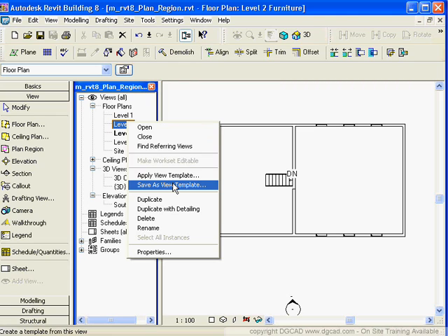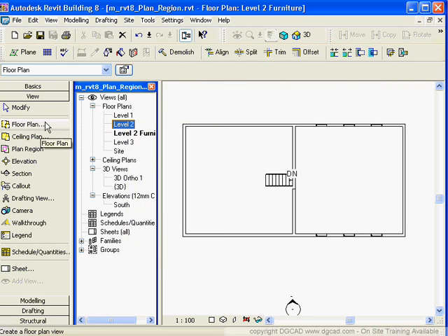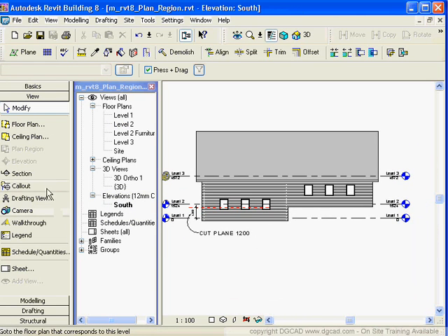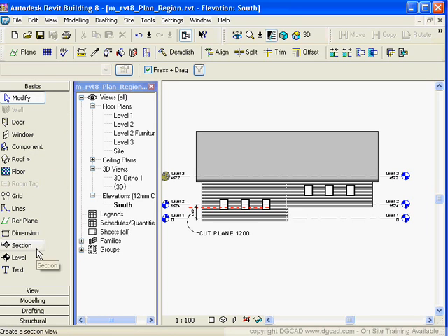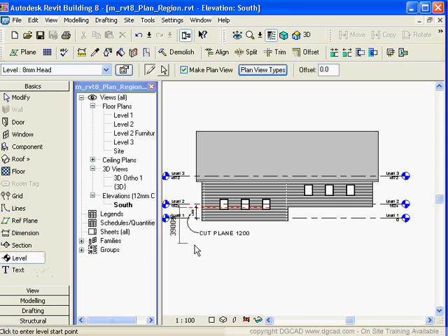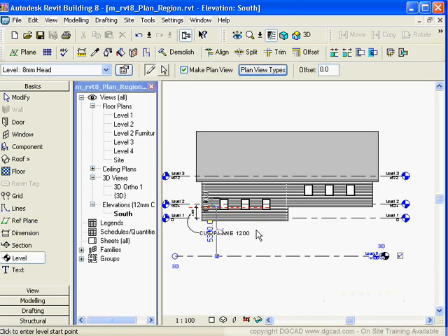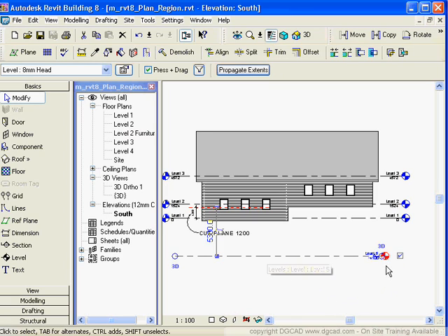And then the best thing is to experiment with that duplicating and see what objects get duplicated and what objects don't. So that's just kind of how we create a floor plan. If you go in and you make a level, if you go down to your elevational view here somewhere, and if you add in a level by going to our basics tab here, and clicking on the level tool, which is only available if you're in a section or elevational view, and I click on that level,